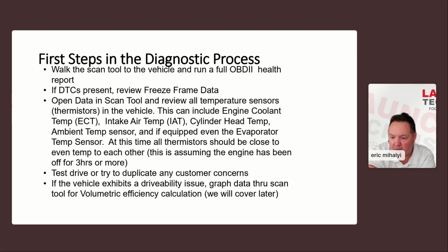Again, it could be a broken wire, but at least it gives you a game plan of going, well, I have to start with that, right? Because the engine coolant temperature sensor on most cars is the alpha male sensor. Almost everything, whether it's fuel strategies or running strategies, are done off of the engine coolant temperature sensor, right? We have a vehicle that's overheating, that car is going to start acting really weird, right?